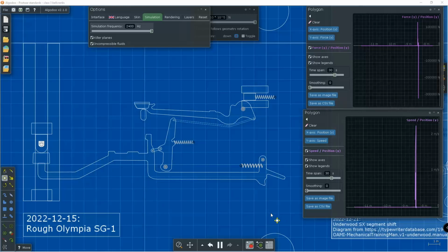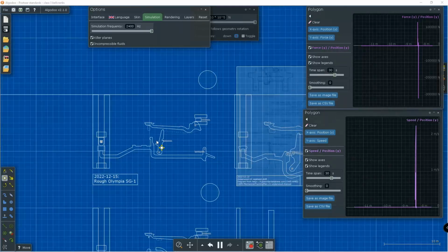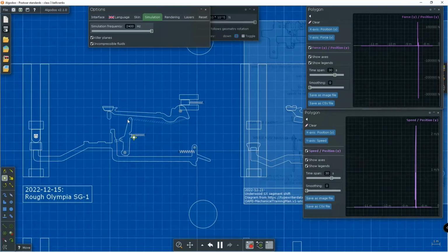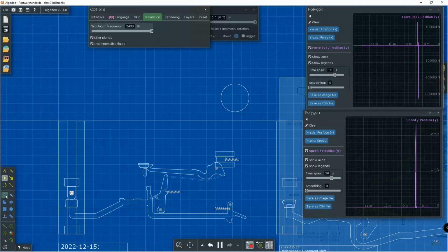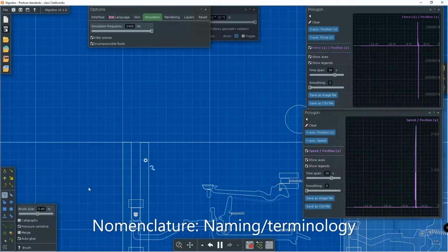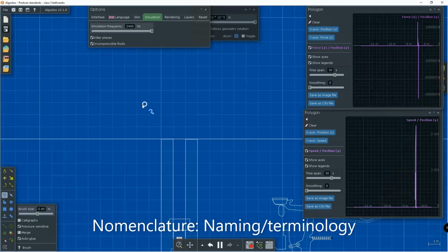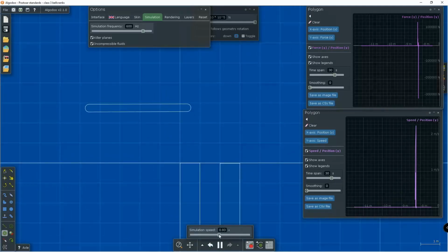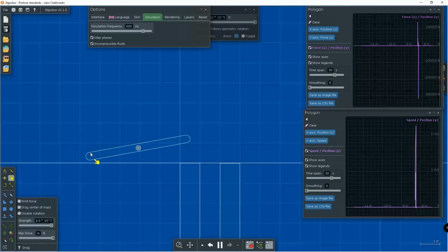Now, what I found surprising is that that style of force curve from that Triumph is actually quite similar in form to that of this family of type actions, namely those that use class 3 bell cranks. So before that, let's first do some nomenclature. So basically, for your levers, class 1 means that your effort is over here, while your load is over here.